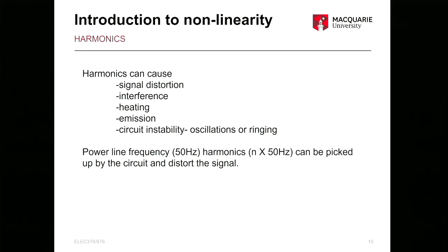So through emission you lose a lot of signal power. And sometimes this causes instability. If you have a circuit designed for a particular frequency range and you have generated some harmonics that have a loop back, that can create oscillations and ringing in this. You have seen ringing, but this is a different context.